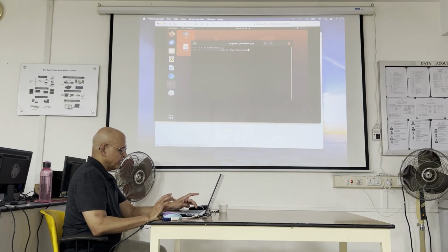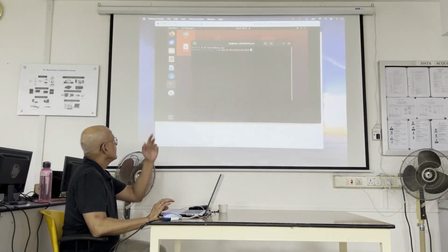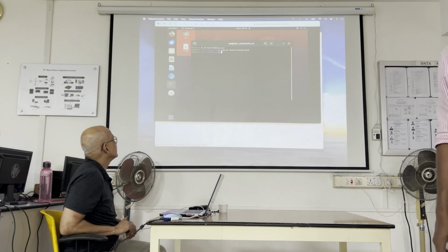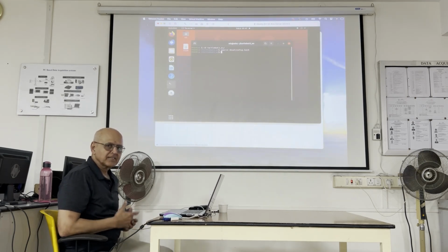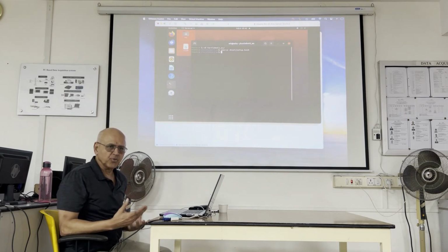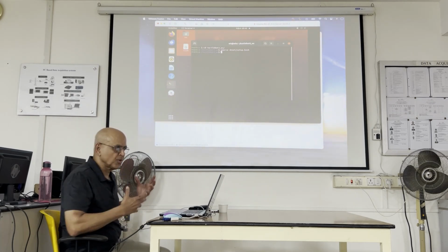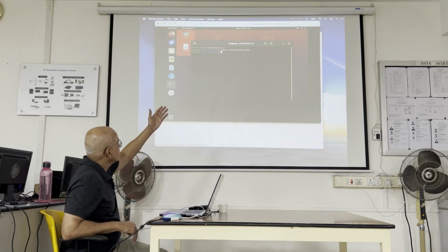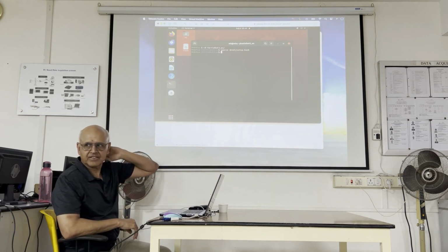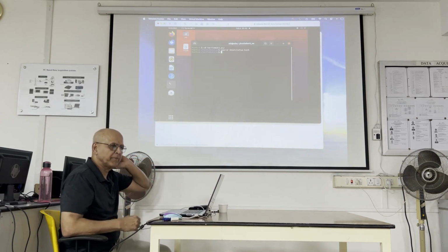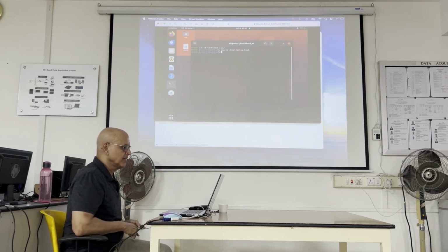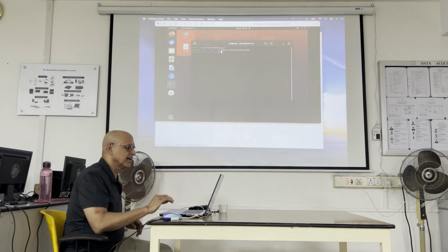Okay, so then I tab complete it again, and I run it. So these 2 things you must do, because otherwise it will not recognize certain aspects of your work environment, the Turtlebot 3 and so on. So sometimes when you think a command should work and it says, I don't know what this is, it's because you haven't sourced or run the setup.bash file. It's very important. So that's the reason. If you go back and source it, then the same command will work. So follow this like a rule book. That's why I wrote it up for you.